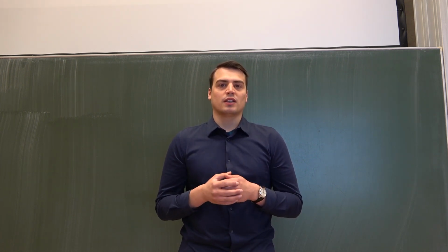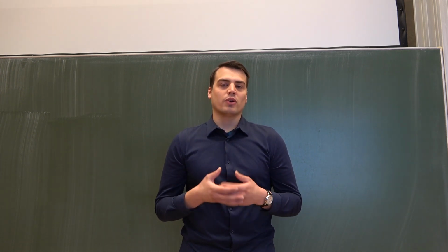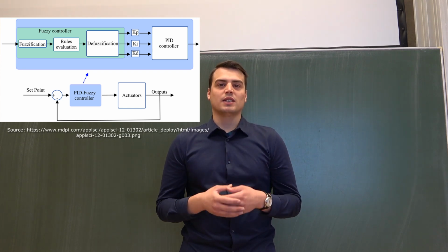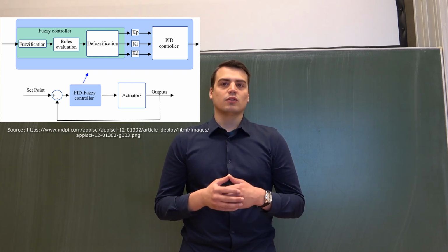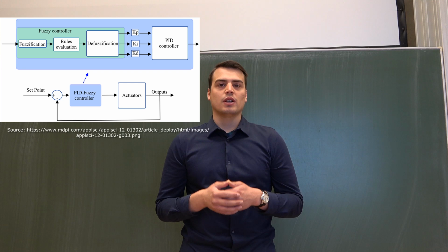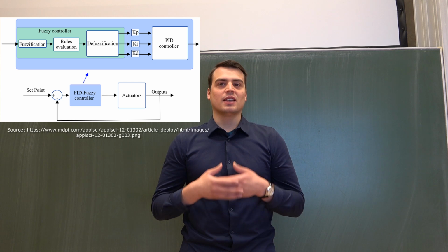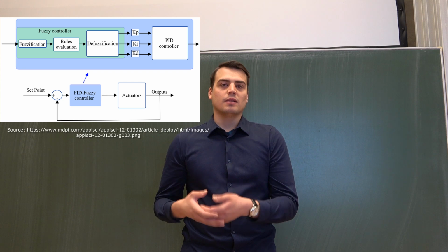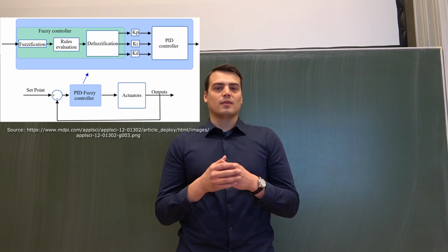The second autopilot technology, which we will explore, is called fuzzy logic control, or in short just FLC. Unlike traditional control methods like PID, FLC does not rely on an explicit mathematical model of the system. Instead, it uses a set of rules based on expert knowledge and intuition to determine the control actions. This makes it particularly effective for handling uncertainties, nonlinearities, and imprecise system dynamics, which are common in UAV systems.